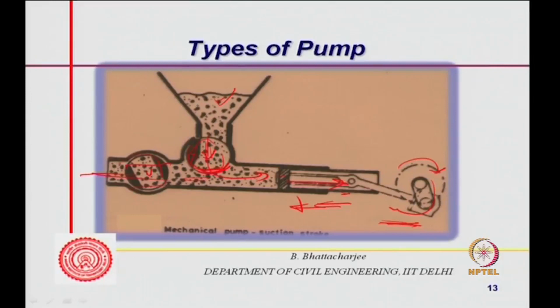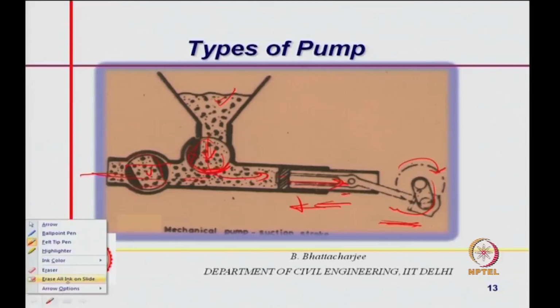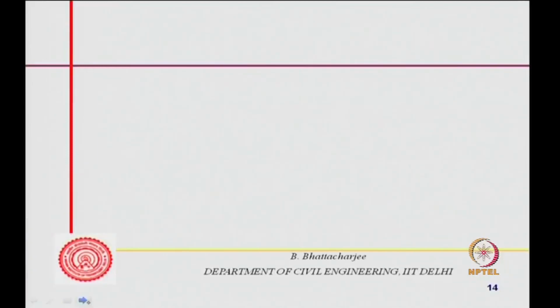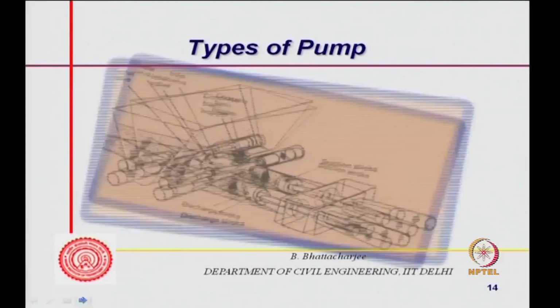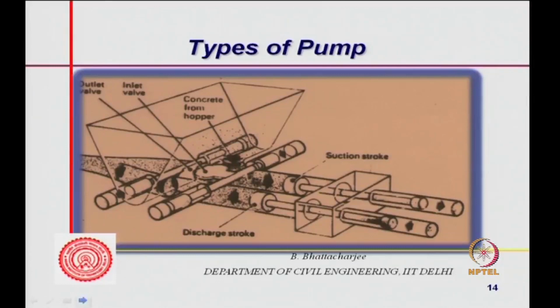So, it is basically reciprocating action, and this is directly mechanical, but this system can be modified to a hydraulic system, and that is what is most commonly used. So, generally you will have a hydraulic system. Now, the same piston is operating, but it is operating hydraulically. That means your fluid is the one which gives the pressure, and therefore, you will not have jerks.